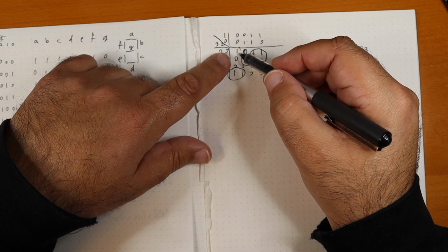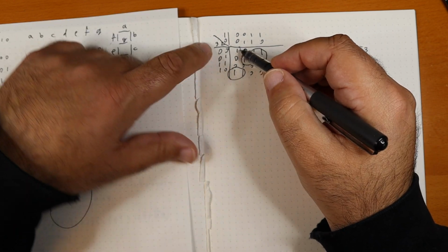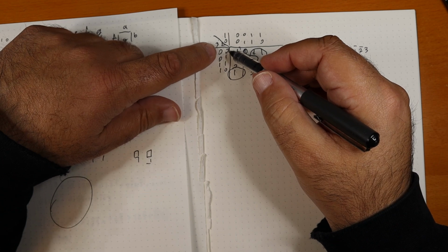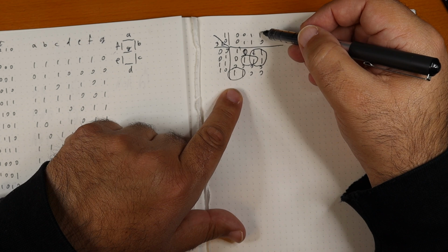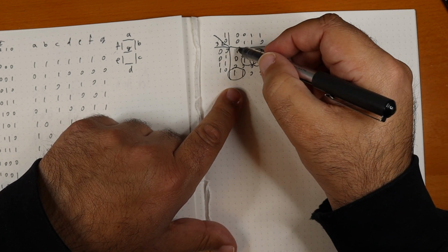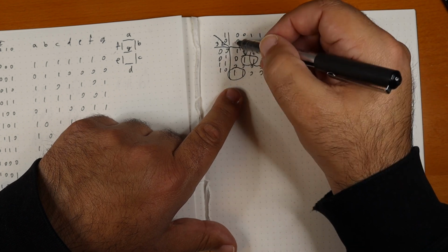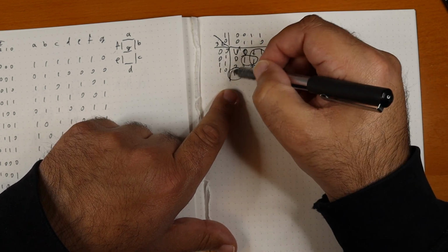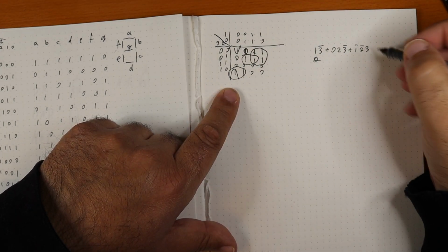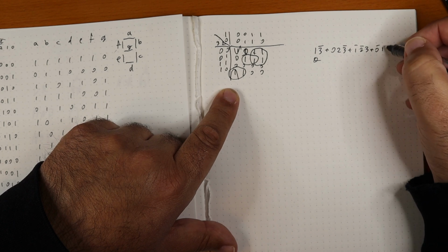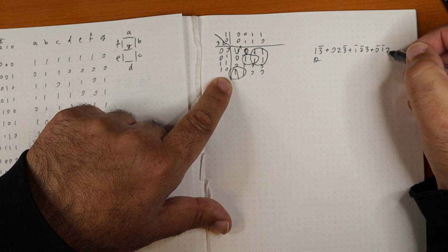And last we have this one. And it seems like it's all along, which means we'll have to specify all 4 inputs. But actually, if you look at this row, it's a Hamming distance of 1 from this row. And this column is a Hamming distance of 1 from this column. So we can actually extend the rectangle either to the left to this one or to the bottom to this one. So let's do the bottom one. So this coverage. And here we have 0 not, 1 not, and 2 not.